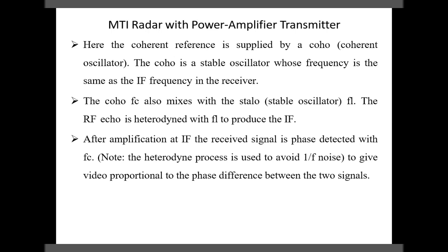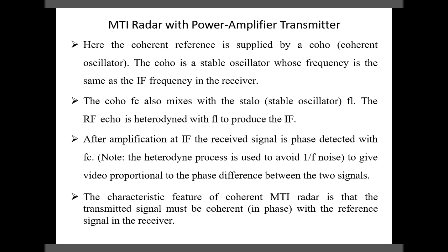That is, the received signal is compared on the basis of phase with the coherent oscillator signal fC. Here we have to note that the heterodyne process is used to avoid the inverse frequency noise, that is 1/f noise, to give the video proportional to the phase difference between the two signals.